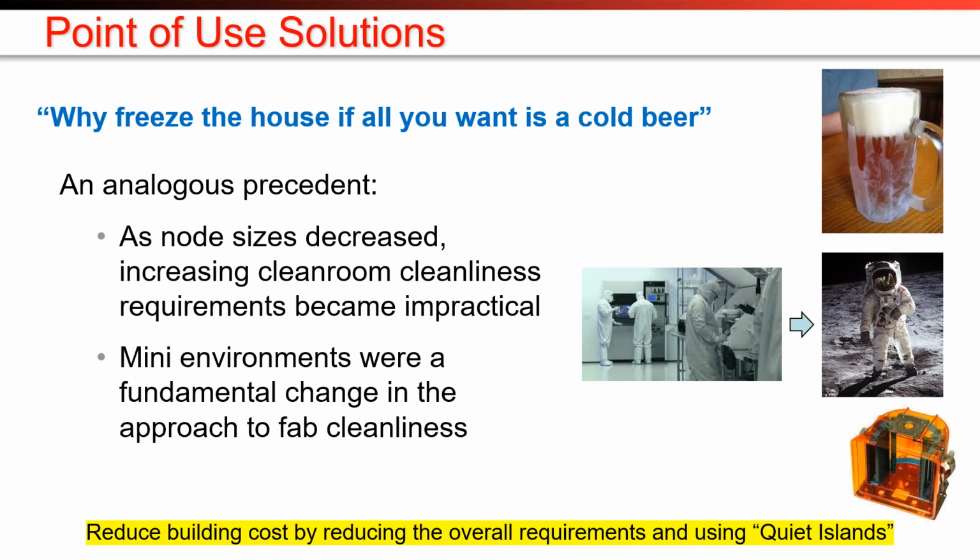And we saw in the semiconductor industry over the course of decades that as each new smaller node was reached, increasing cleanliness of the clean room was required so that you wouldn't have contamination of the IC. Smaller and smaller particles would be able to lead to a failure on an IC. So the cleanliness specs were getting so extreme, it became clear that it was unsustainable.